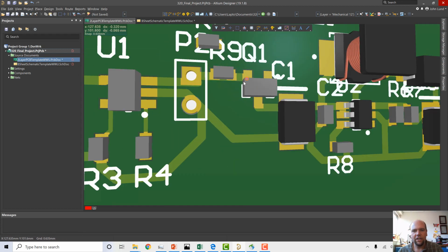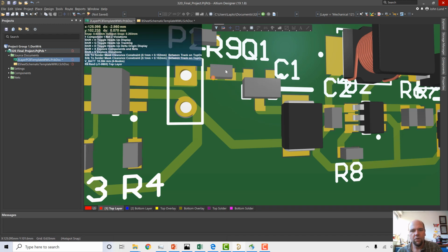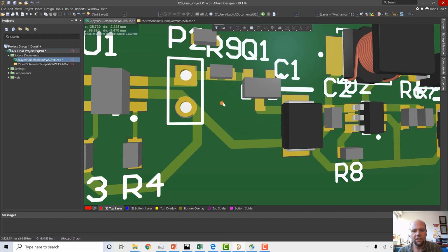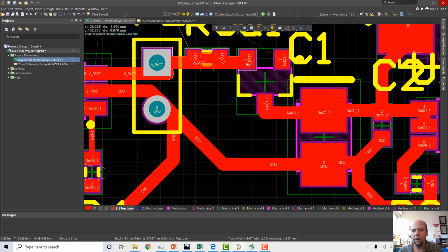So now we've got a resistor here, and what's important to note is that underneath this resistor are two exposed copper pads. So normally this resistor is going to be a resistor that we don't populate. So normally we don't have to put anything here. We just have a wire going straight across here. But if something goes wrong with this part of the circuit, what this allows us to do is we can come in with a razor blade and cut this right down the middle. Then after we've isolated it and figured out what's wrong, we can piece this back together.